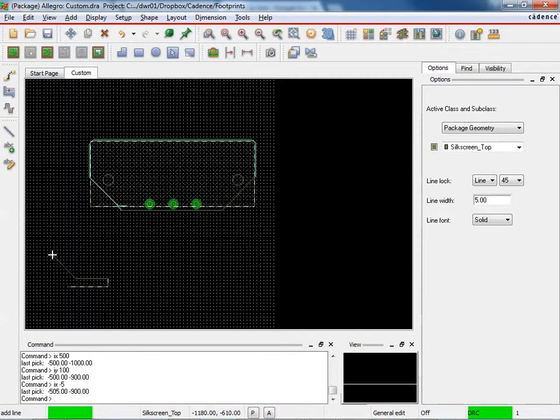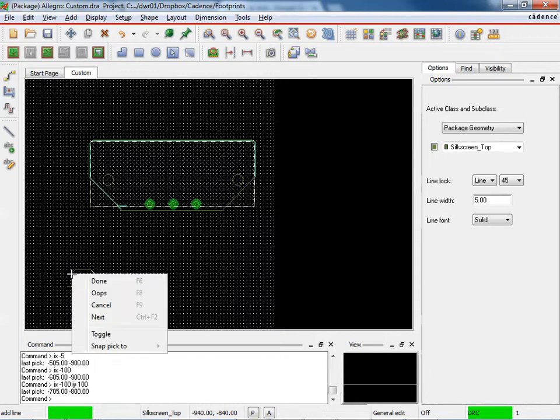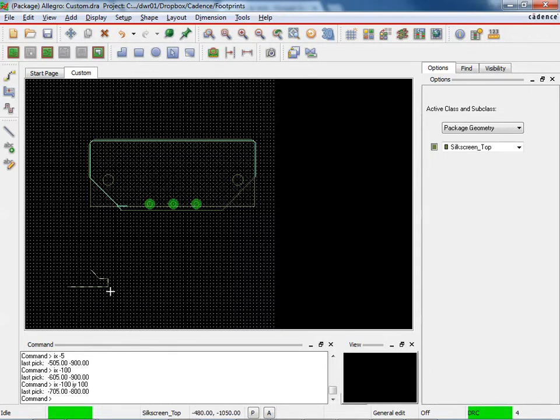And it doesn't really show that here very well. Let's do another increment X of minus 100. Okay, there we go. And then let's do an increment X minus 100, increment Y 100. And then you get a diagonal line. So that's how I actually create those components here, but the video is getting a little long, and so I didn't want to spend the entire time doing it. But you can get very accurate ones by doing those increment commands. So let me just delete this.